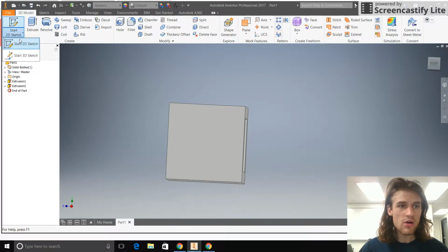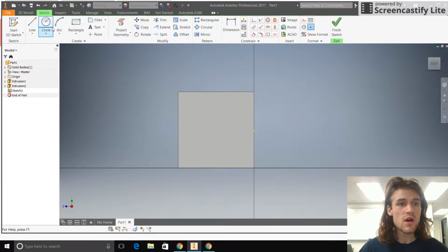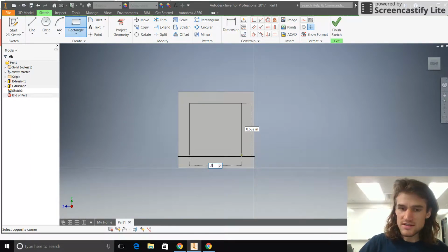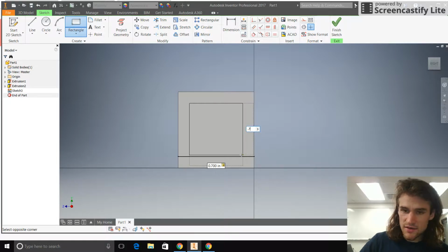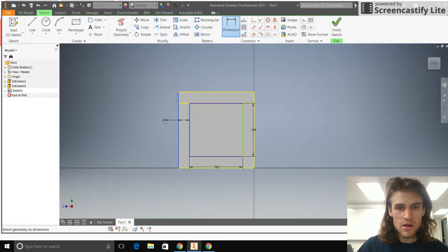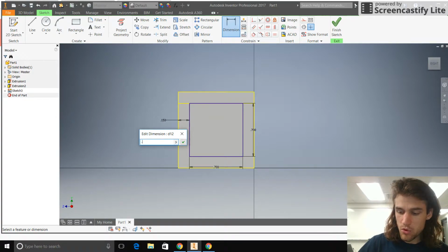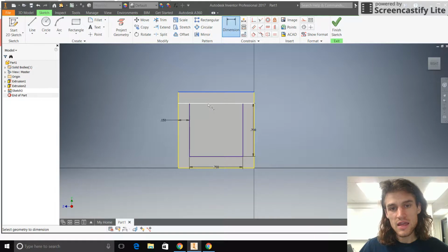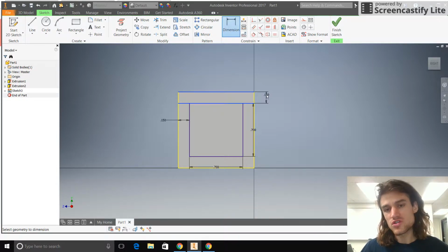Let's keep on doing that. I'm going to go kind of quick just so the video doesn't get too long. You can follow along. You can do what you want. Let's see. Oh, and look at that. This popped up through here. Maybe that will be of some use. 0.7 tab, 0.7 tab. Okay, there we go. Now let's project the geometry here. And we will dimension again here 0.15. And here, now I might get some issues. It's already okay. So it won't let me dimension here. It's saying if you dimension here, you're going to over constrain the sketch.